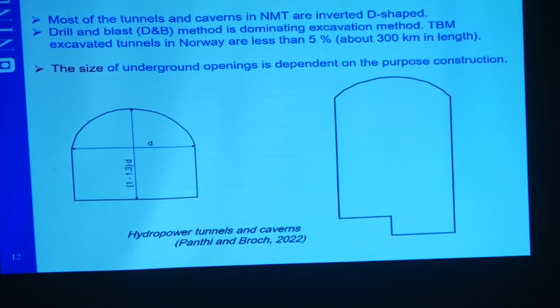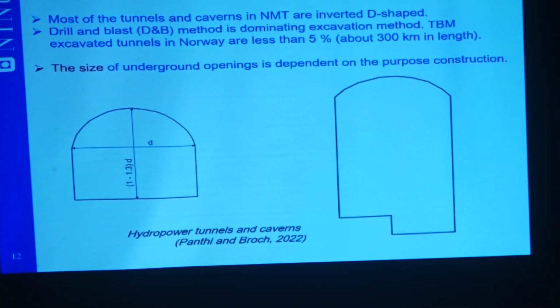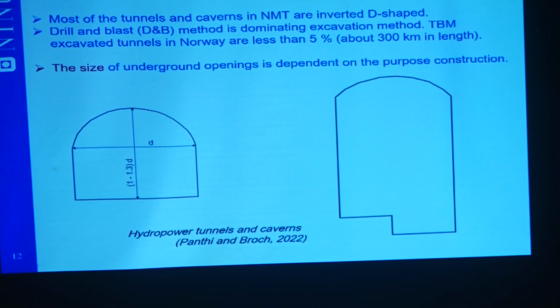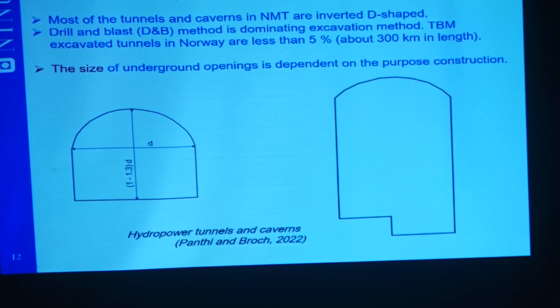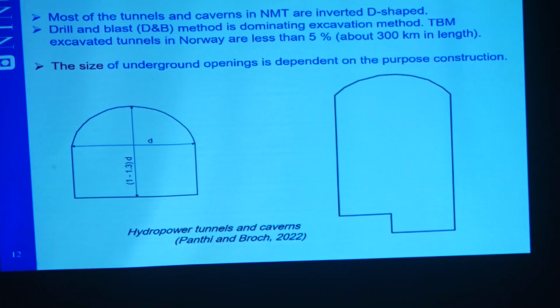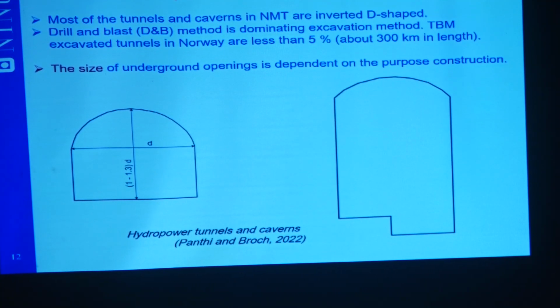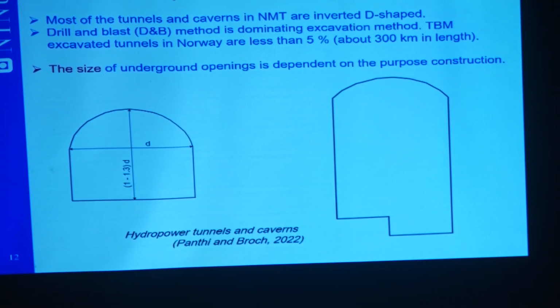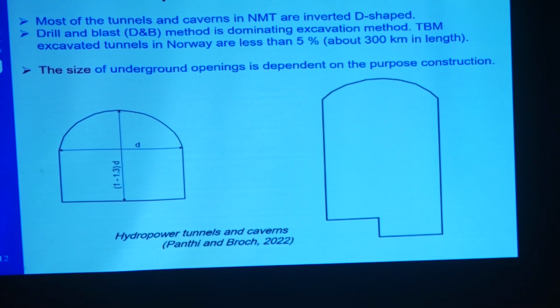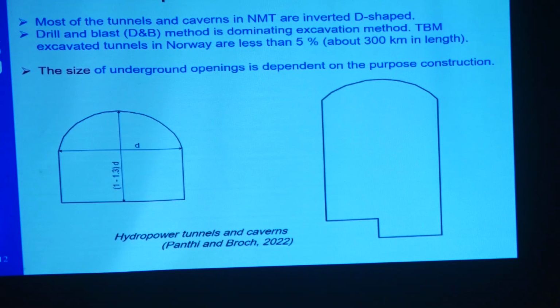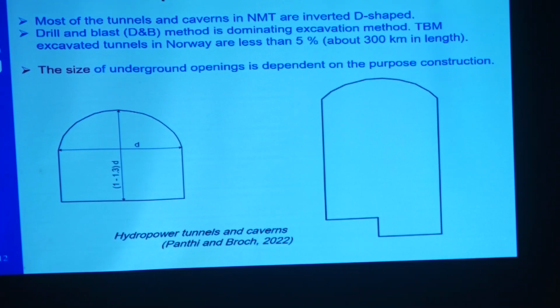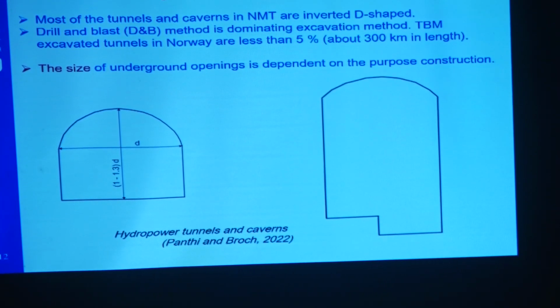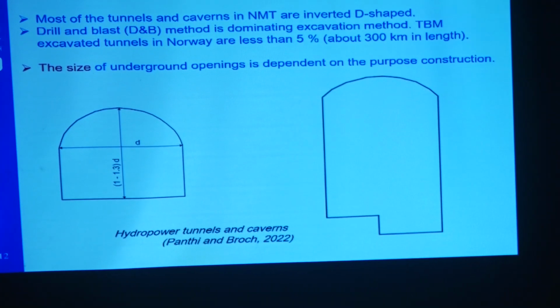It will be the same case in Nepal. There will be some headrace tunnels in the projects, two of them are completed, so it was okay for that. And maybe if we have a very long tunnel system, we may use TBM. But TBMs are at least 2.5 to 3 times more expensive than drill and blast. What is important is Nepal should use the technology to do good drill and blast tunneling, because the present practice we do is insufficient to have very efficient drill and blast tunneling.